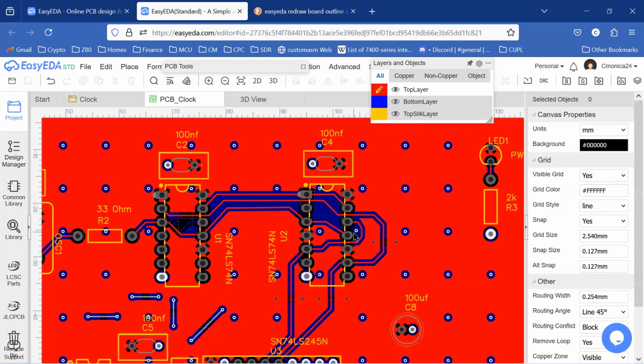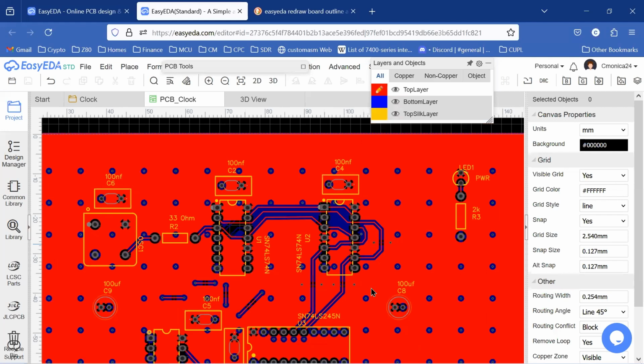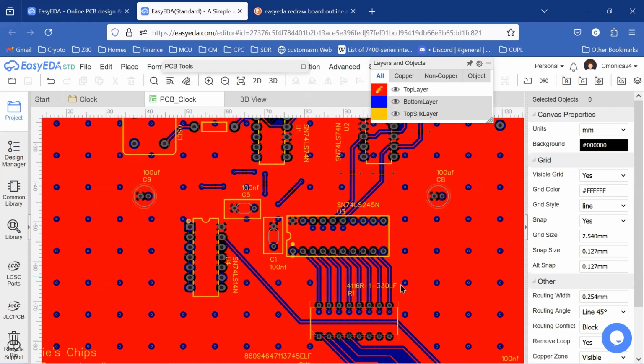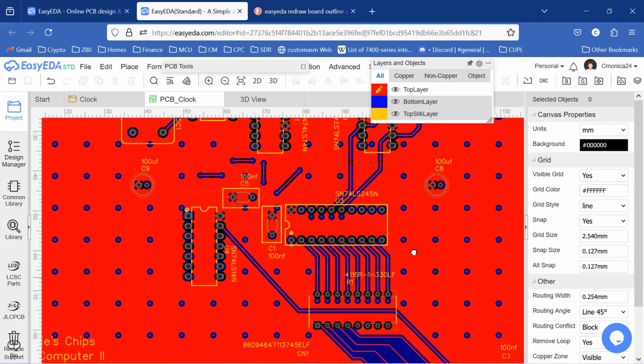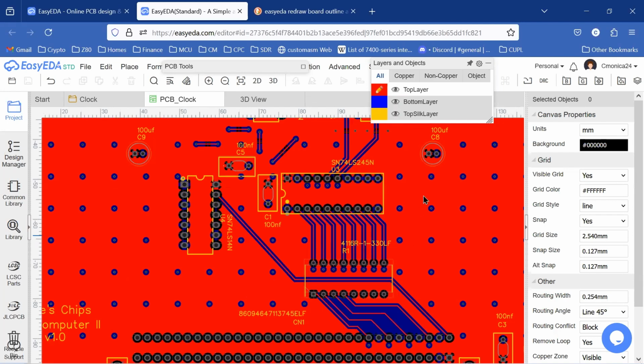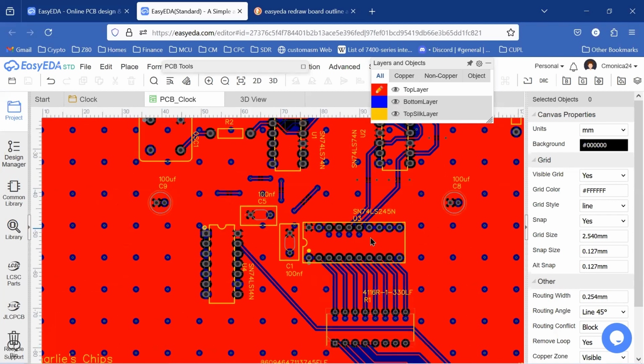And here, these vias also, they're a key element in PC board design. Look up return path vias in Google, and you'll find tons and tons written on it, and it is a key design element for signal quality in your boards. And I have placed those vias in key locations here.